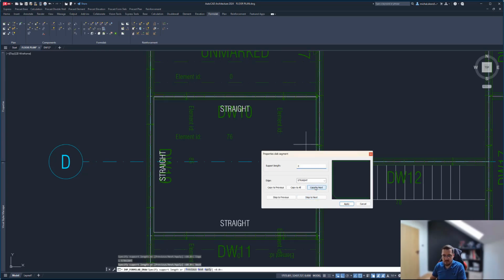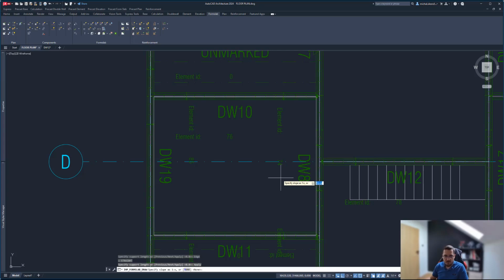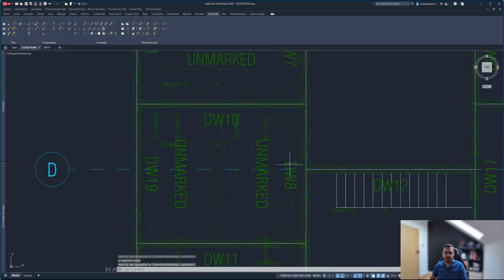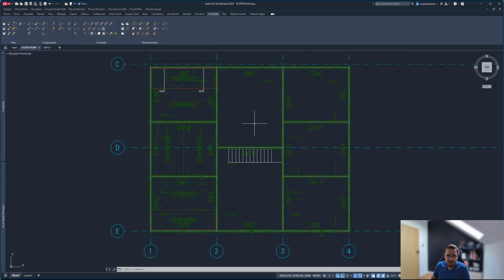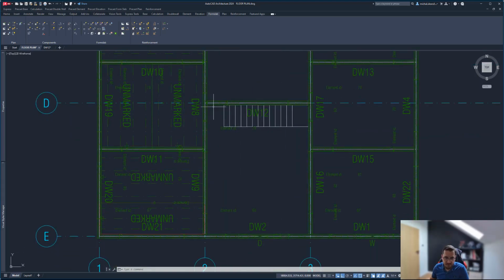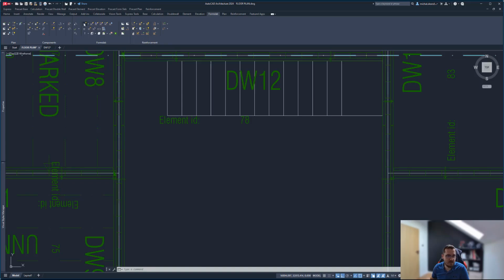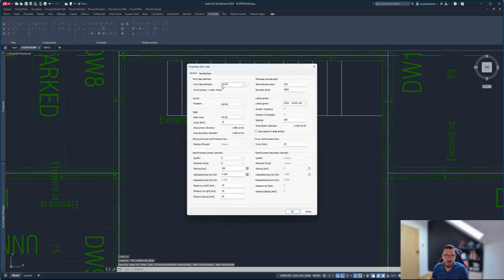This is not. Step to next, 80. Step to next, and 0. Yeah. Right, no slope, and for example, we can leave it as like this. And this actually makes it fit two slabs perfectly with no cuts in this direction. And with this done, let me go ahead and actually add the last set of slabs here, just so you can see how fast it is and how easy it is.